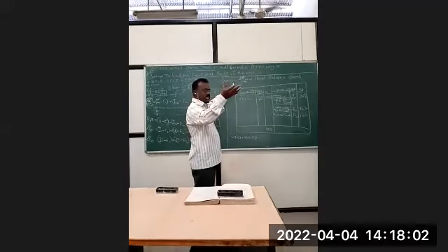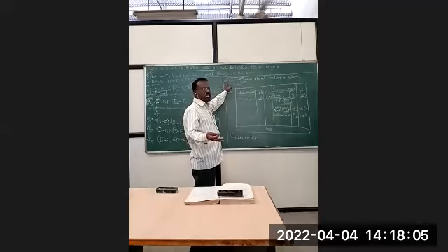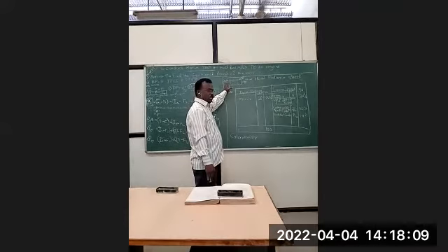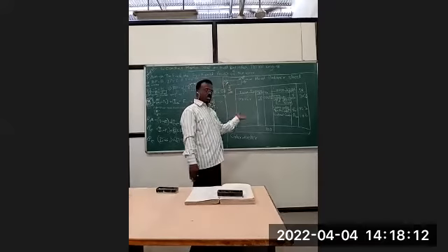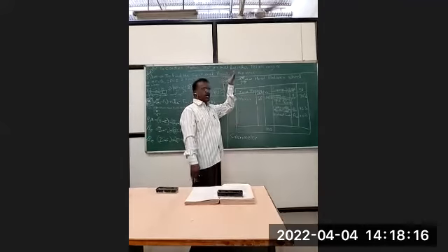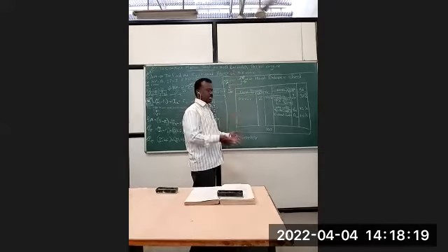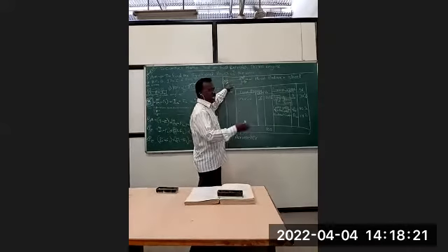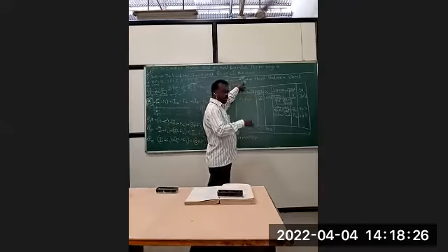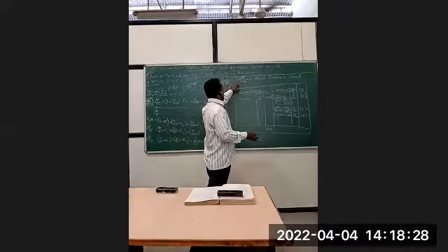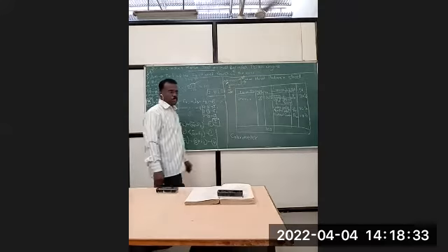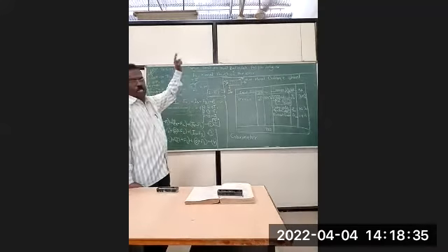Air was given to the engine at atmospheric condition, then heated up by compression, combustion, etc. So whatever extra heat was added to the charge is taken out and given to the water. So heat lost by the gases is equal to heat gained by the water.